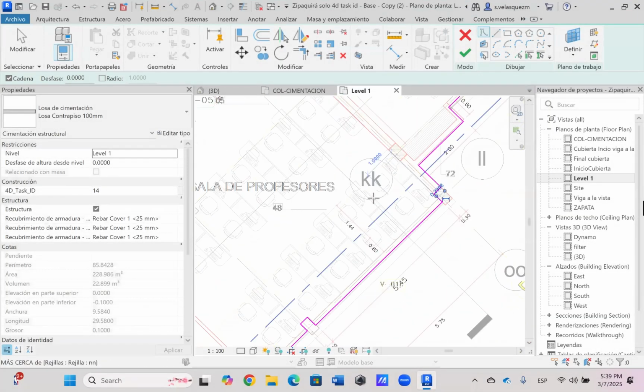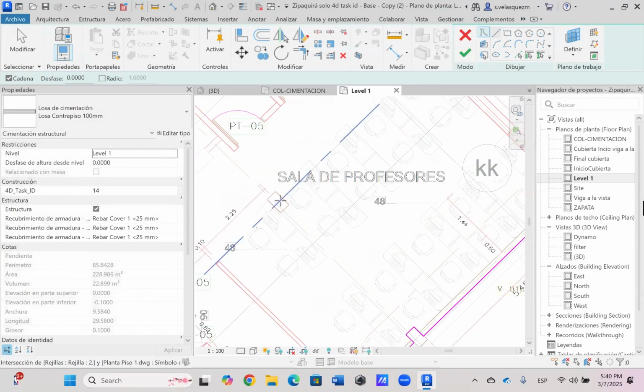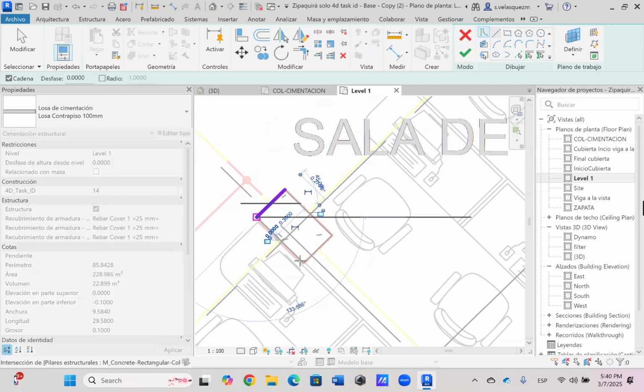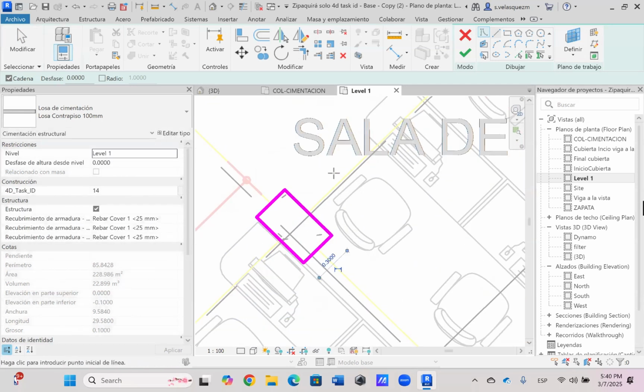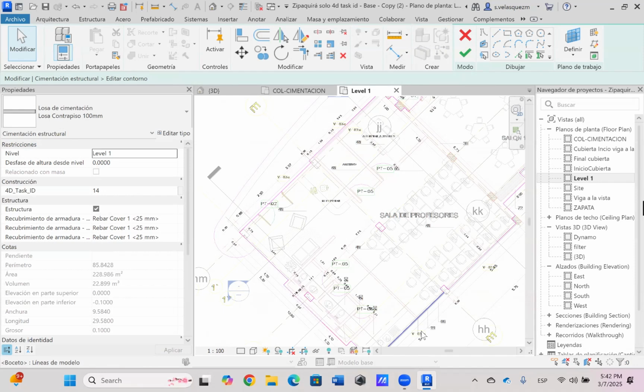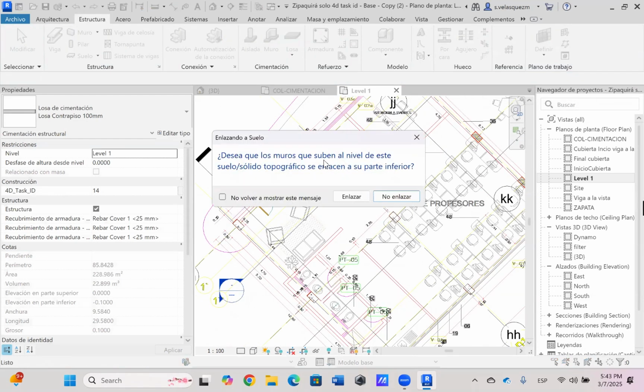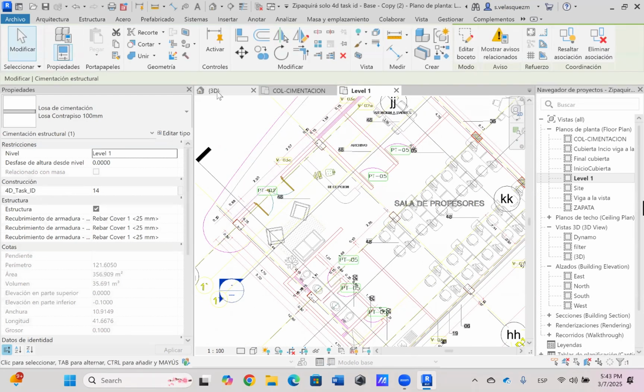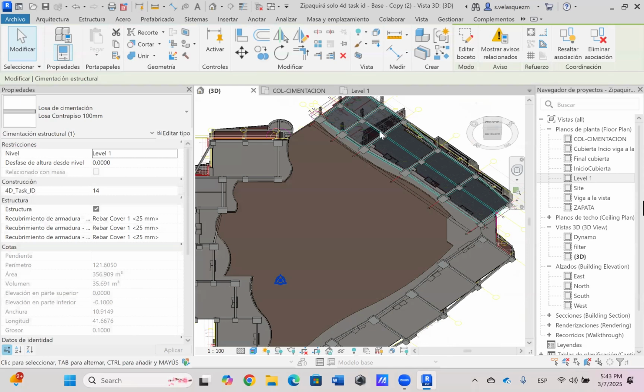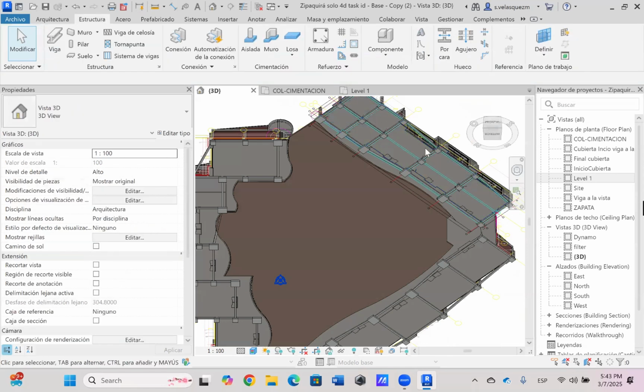Once you close the sketch, you can also draw around any interior columns, and Revit will interpret those outlines as voids or openings within the slab. Now, the slab sketch should be complete. To finish, click the green Finish button. And just like that, the slab should now extend continuously across the entire block. As we can see, the whole block now has a complete floor slab.